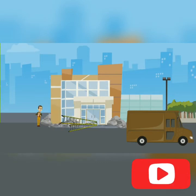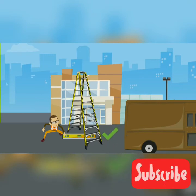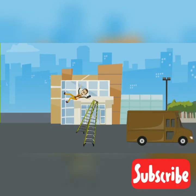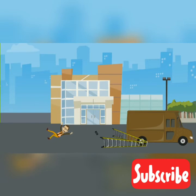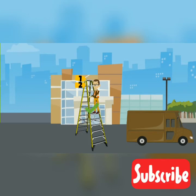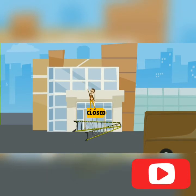Never set up a stepladder on an uneven surface. Each of the feet must make firm contact with the surface of the ground or floor. Never sit or stand on the very top of a stepladder. In fact, the recommended rule by stepladder manufacturers is to never stand on the top two steps. If your knees are above the top of the stepladder, you are too high on the ladder.